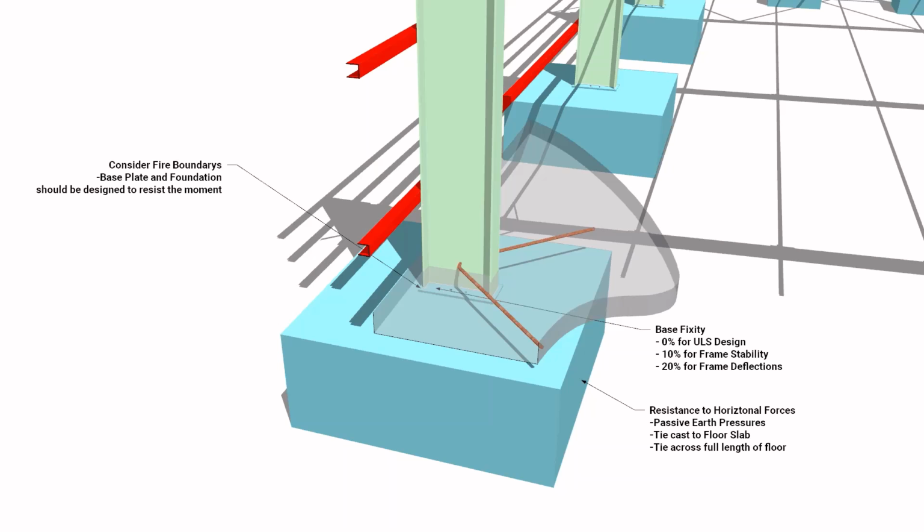Also to note, horizontal forces on the bases from wind can sometimes be troublesome when you have large wind loads on a lightweight structure, or if the base is kicking out, which is part of the behavior of portal frames. And so relying on passive earth pressure can be unreliable, and the sliding resistance from friction of the foundations on the soil usually is not enough, and it will require oversized pads to generate enough friction to provide resistance